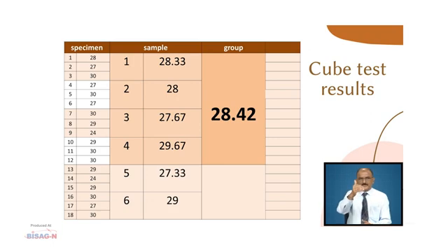Just because one value is very less, in the sample 1, 2, 3, 4, the sample number 4 is having a very less value. So, we will just discard it, we take 1, 2, 3 and 5, that is not acceptable. So, it is non-overlapping, consecutive test report should be taken.